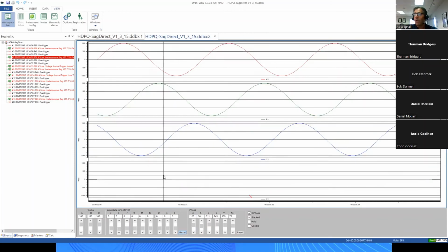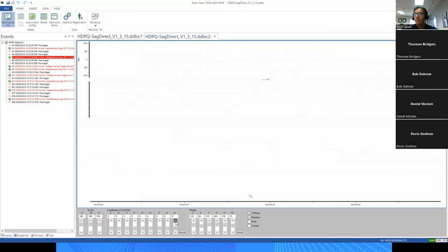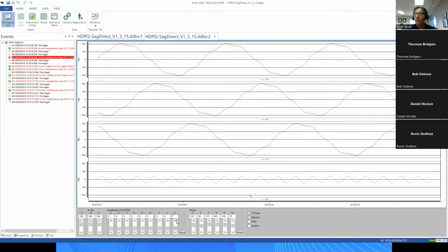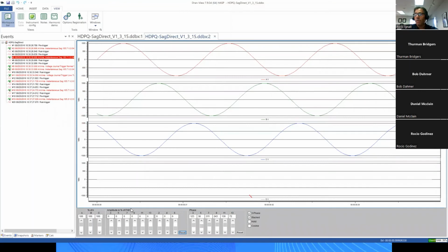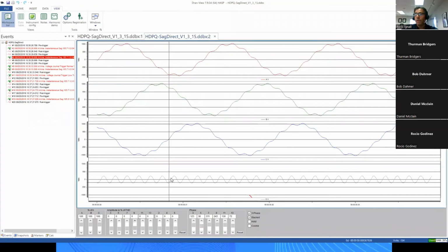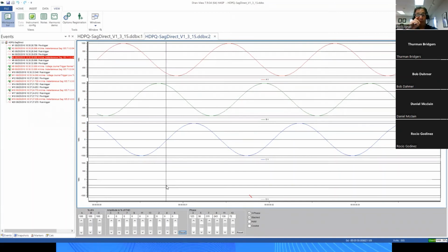Reset again. We talked about before the even order harmonics. Even though the 6th is a triplen, even harmonics typically don't appear in most power systems, but mathematically, it's still there. So you can see I just randomly put in 7%, and you can see its effect on the neutral here, okay? So you can see the 3rd, you can see the 9th. You can see how that adds in, and you can see how that goes up. So this is a visual effect of the triplen harmonics.